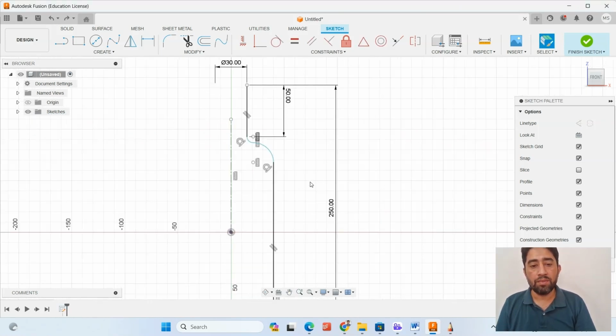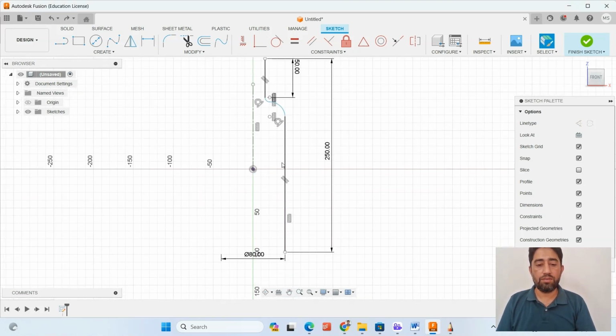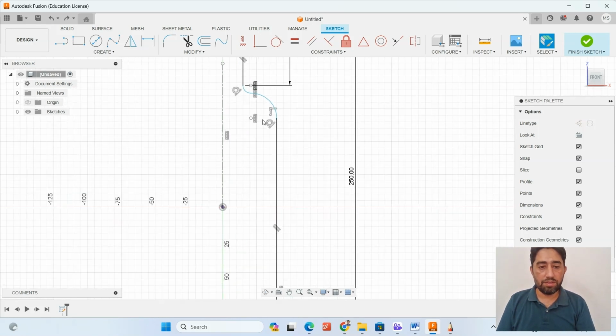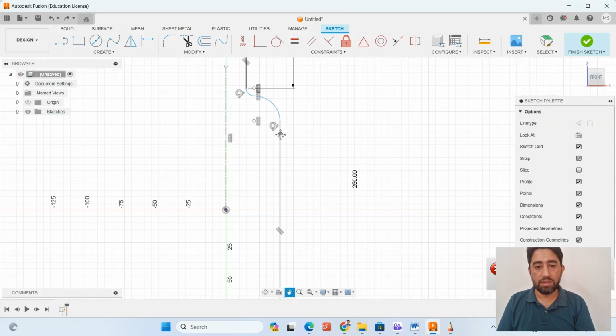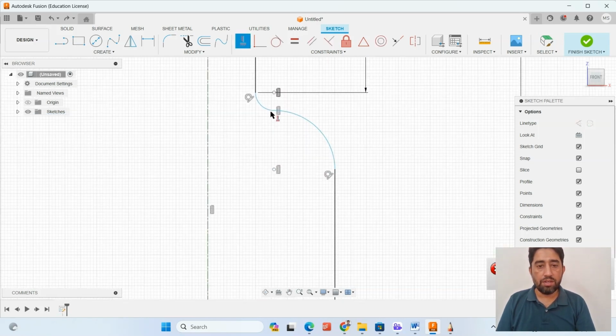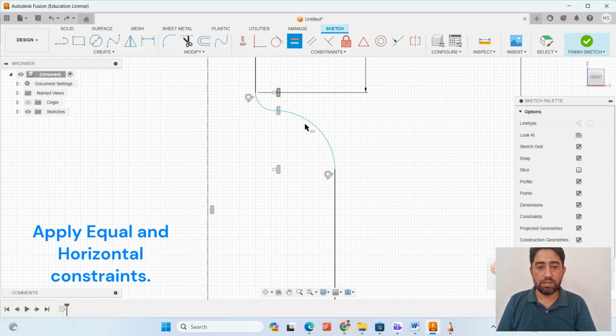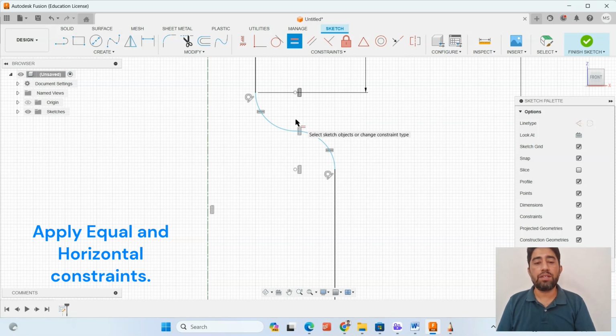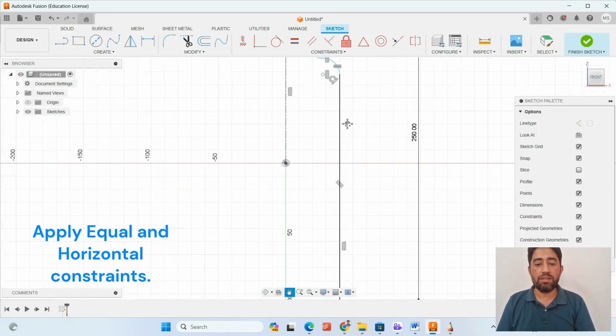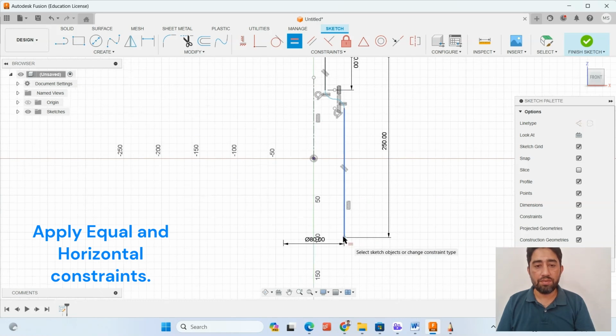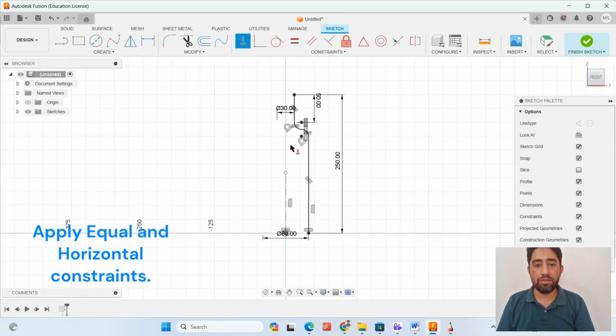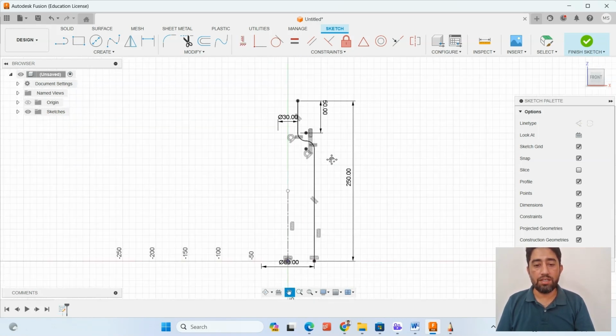Now it goes beyond. The bottom point of the bottle goes below the origin. So what we have to do first, we will define these two to be horizontally aligned. We can't apply over-constrained geometry. Make these two arcs equal, which is the first way of applying the appropriate constraint, and then we can make this bottom point coincident with the origin. So now it is completely defined.